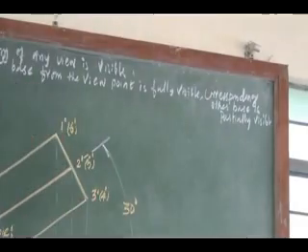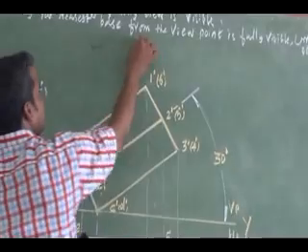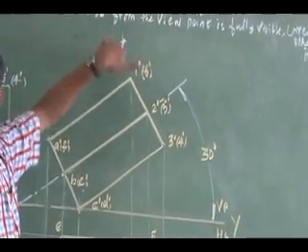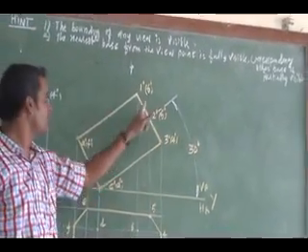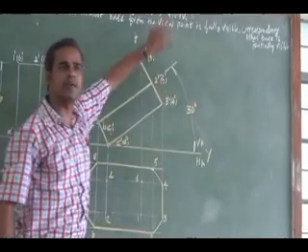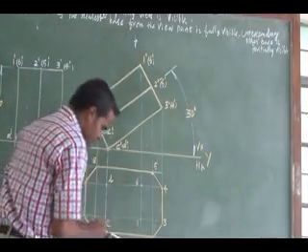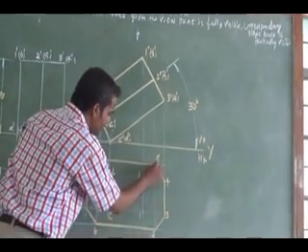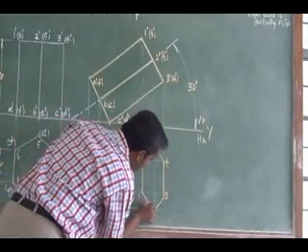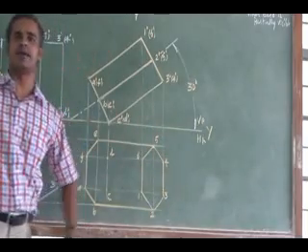Right. So you see, to draw the top view, I have to look at it from the top. Which is the nearest base I have in both these bases? Number 1 or letter 1? Number 1 is fully visible. So this base is fully seen, so I can draw it as a fully visible one. This is a base, so that base corner I can draw as a fully visible one. Already half the portion in the boundary I have, so I can draw it as a fully visible base.